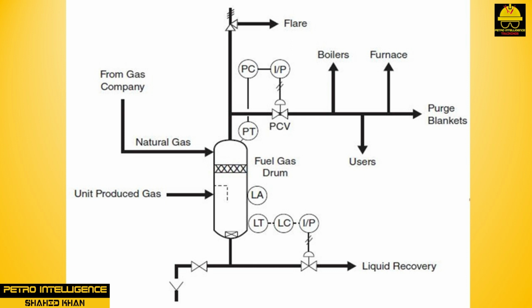The letdown/meter control valve is in operation at all times. A second valve opens when the flow rate is high and closes at low flow rates, thereby making possible more accurate metering of the gas flow. The plant natural gas distribution header normally runs around 200 to 250 psi. Each process unit has its own pressure control station that usually maintains the unit pressure between 60 and 100 psi.